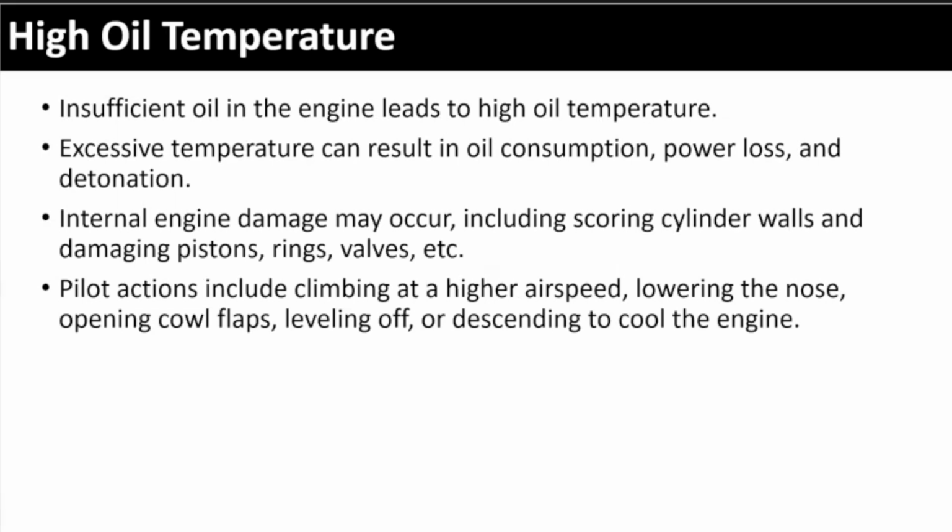Planes are different. Plane engines are manufactured to not burn oil like car engines do. So it's normal after several hours to have to put a quart of oil into a plane engine. That doesn't indicate a problem. Planes burn oil and you just need to keep track of it. That's why it's so important during the pre-flight to check it. You can go from above 6 quarts to below 6 quarts in an hour flight. Questions?